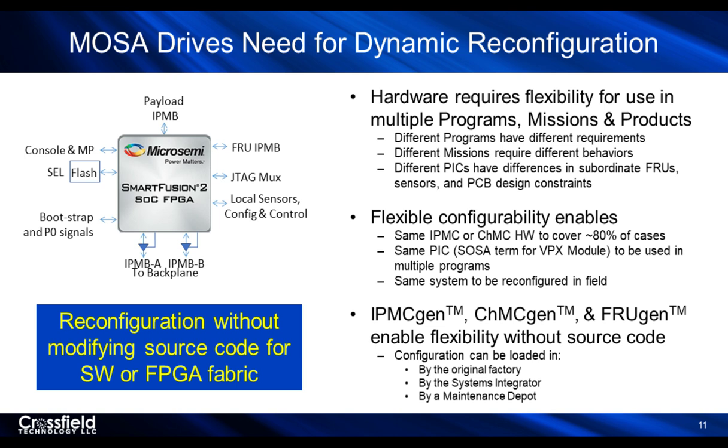The concept here is that you don't want to be messing with low-level code in order to provide a new function. If you have to go in and mess with very low-level code, now what you've done is opened up this whole bag of verification worms that you have to avoid. So you control these capabilities through commands you built into the IPMC or through controllable things that can be verified in advance, that these different configurations will work.